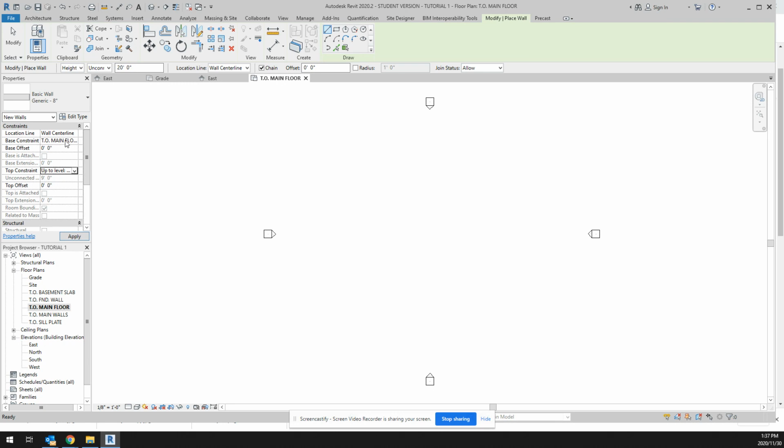Now, whenever you're drawing your plan, you want to make sure again that you're drawing it in between these view indicators. Never eat shredded wheat: north, east, south, west. As you draw, if I drew part of my walls outside of these view indicators, then when I generate my elevations, I would be missing part of my elevation because it's not within the view range. So when you're drawing your lines, keep things to the middle of this area as you're drawing your walls.